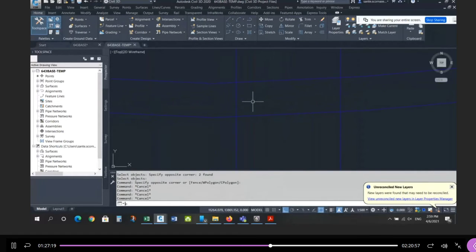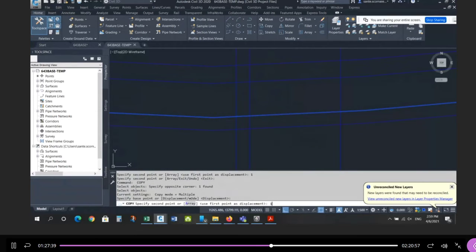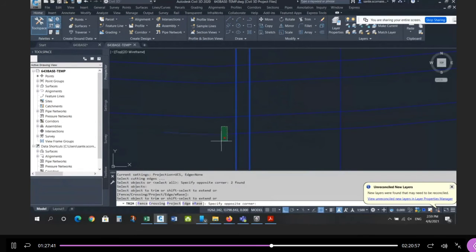So what does the plug look like? Well, I'm just going to offset 0.75 on this side. I'm going to make a copy of this, 0.075, maybe more. Copy this up 1 meter, copy this down 1 meter, and then trim it on both sides, and then trim this here and here, and the original line was here. There's what your plug looks like.